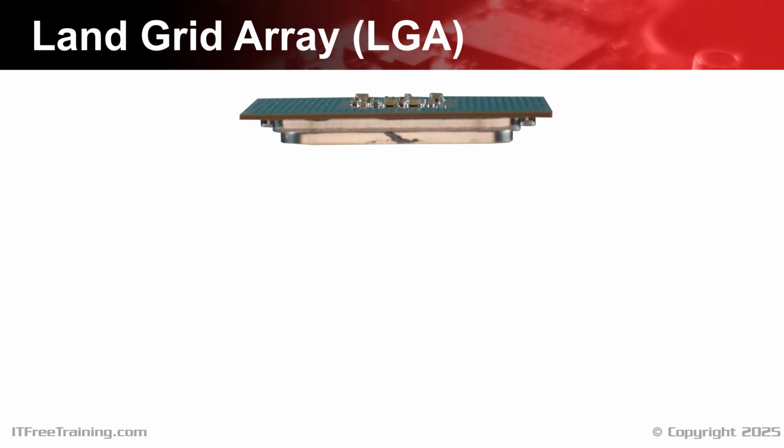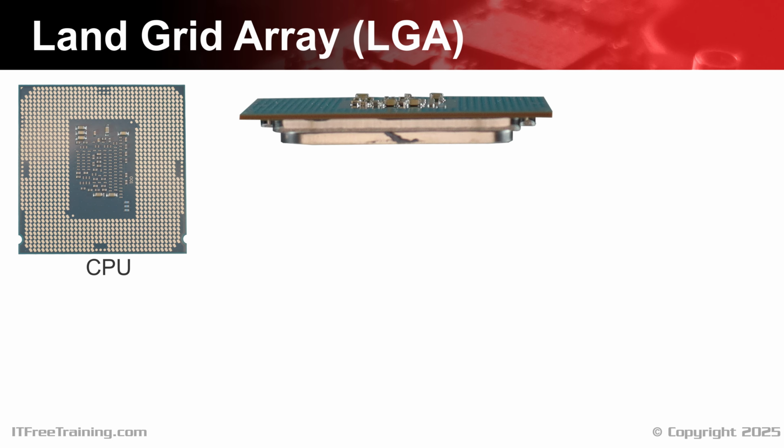Intel have released over 10 different sockets using Land Grid Array, or LGA. You can see this on an example CPU. The bottom of it is flat other than a few electronic components. Looking at the top of the CPU, you can see all the contact points under it. They're quite small and difficult to see. If you were to count them, it would add up to the number after LGA. In this example, the CPU is an LGA 1151, so there would be 1151 contact points.